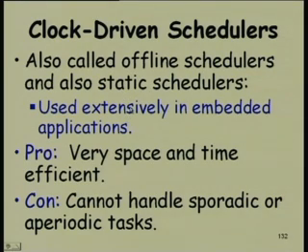The concept is very simple, but used extensively in embedded applications. Actually, I visited some of the industries which manufacture embedded applications, and I asked them what kind of operating system and scheduler they use. They said, we use only clock driven schedulers because our applications are simple, do not need anything beyond that, and it is most efficient and simple, and you can manufacture devices cheaply which produce the desired result.